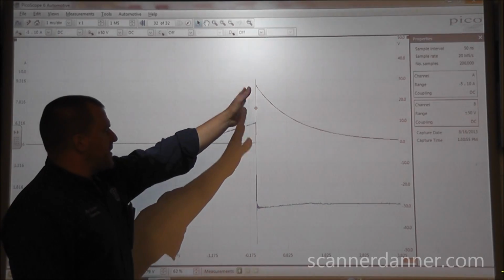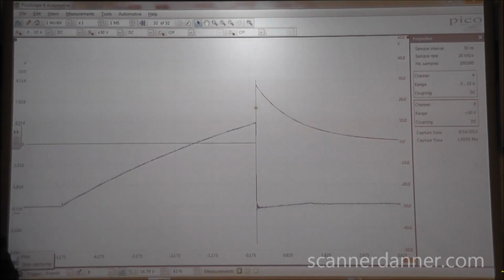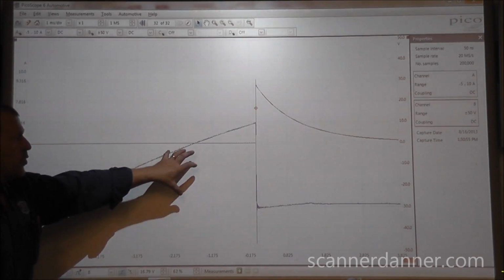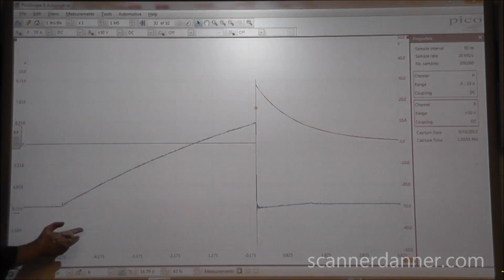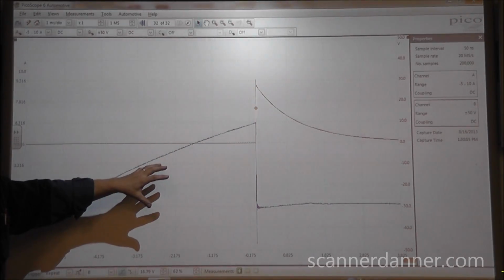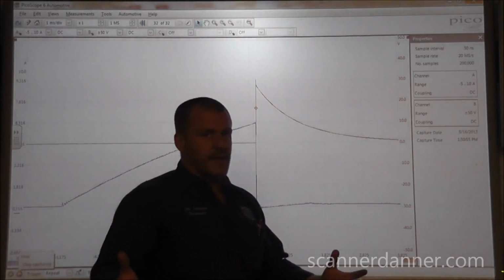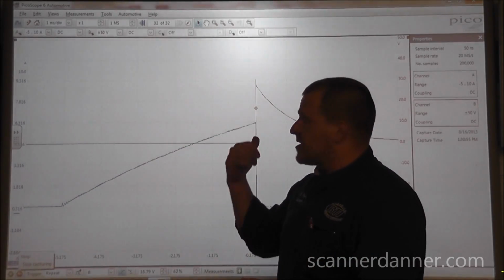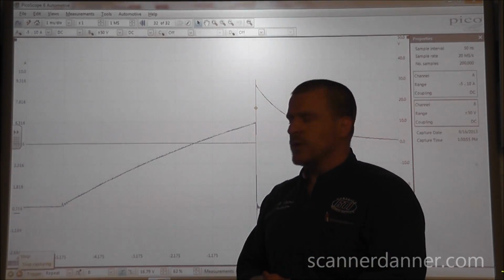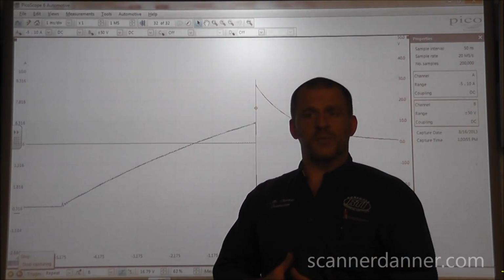You trigger off of a different cylinder and it will pull everything together or out of, in our case, channel A, where all 6 are firing. We pulled out the number 1 only ramp. This ramp, this event, is the number 1 cylinder firing. And that would be what else we can do with trigger. So hopefully you guys like that. And we'll do more with sampling and time base and some other stuff at a later time, but I think that's a good intro to scopes, and the stuff that we're doing here really applies across the board to all scopes, not just the Pico.